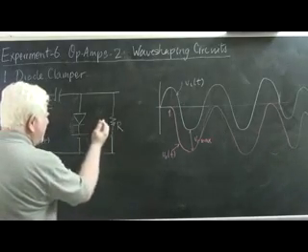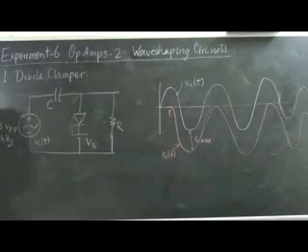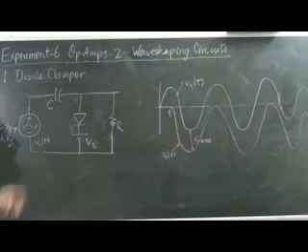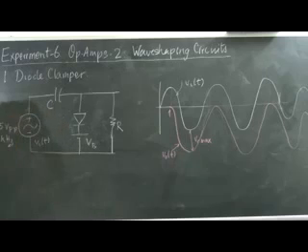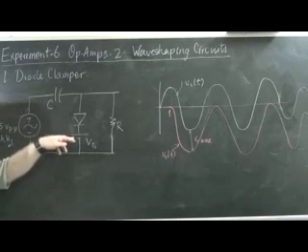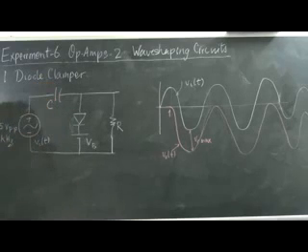Now if we have a non-zero battery voltage over here, what that would do essentially, depending upon the polarity of the battery and the magnitude of the battery voltage, would be to further bias the turn-on voltage of this diode either positively or negatively. If you set it at a positive value, the turn-on voltage would be shifted upwards.